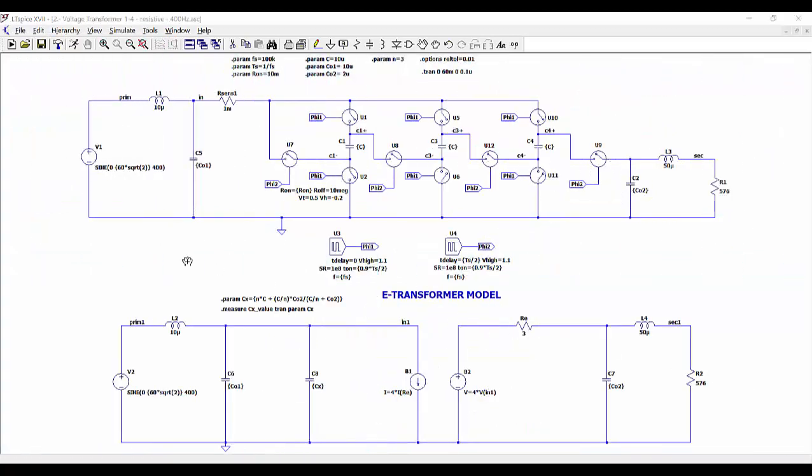We have seen also that the dynamics of our circuit is very good, so we can think about using our voltage transformer in other applications at higher frequency. For example, here we are applying at the input 60 volts RMS, but at 400 Hertz, as in airplane applications, like this also here in the model.